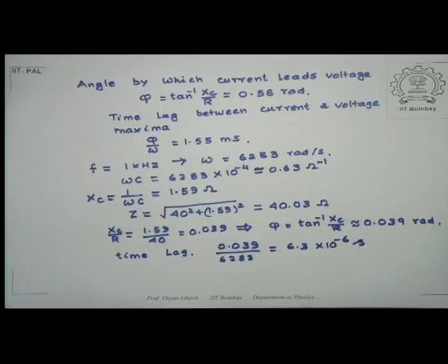So you notice the current is gradually becoming almost in phase with the voltage. In other words, as I increase the frequency of supply, the capacitor is becoming more and more conductive. Remember, for a DC, the capacitor was an open circuit and did not allow the current to pass. So with increasing frequency, the capacitors turn out to be more conductive.